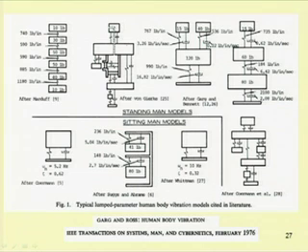Or one can develop another type of model where this portion can be represented as the spinal cord of the system, with different spring and mass damper systems. Starting from the leg to the head we can attach different springs and masses and convert the human body to a different dynamic model, and this dynamic model can be simplified.